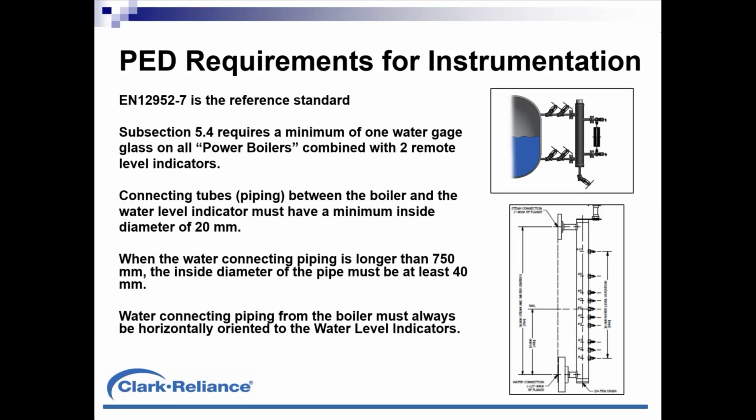We'll be discussing an appropriate and proper blowdown method for level instruments here before the end of the presentation. But some instruments, and I put an example sketch here, the one in the lower right-hand corner of the slide, show a smaller flange, 1 inch size at the top and 1.5 inches at the bottom. 2 different sizes. Of course, the flange faces have to line up perfectly, but this was to meet a requirement that this customer had. Of course, it would be easier to make both pipe sizes the same size.